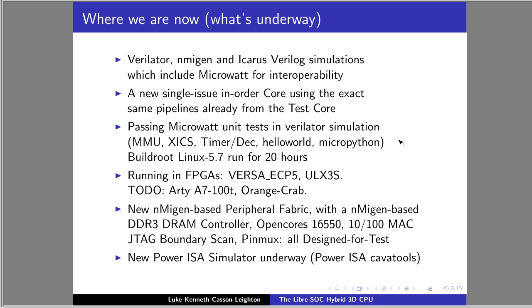What we're currently doing is there's a student, Jean-Thomas, who did a port of LiteDRAM to Nmigen, and he found a Micron Verilog model, joined it together with the ECP5 Lattice models, and with this DRAM controller that he developed, did a cycle accurate, timing accurate simulation of his DRAM core as a DDR3 core as a test.